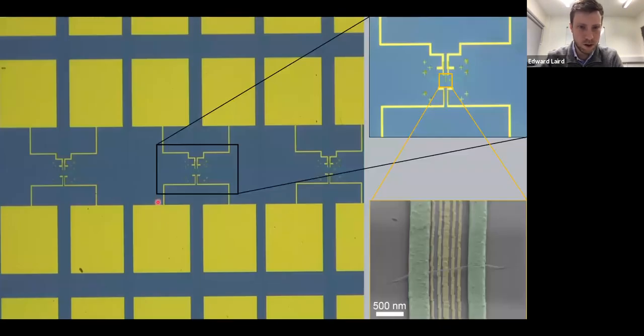So this is an optical image on the left here, where you can see the bond pads and the wires running into the device. This particular device has two gates per nanotube, and this is a high optical magnification. You can faintly see the electrodes here. You can see catalyst residue on either side from the stamping, and then this is a different device.